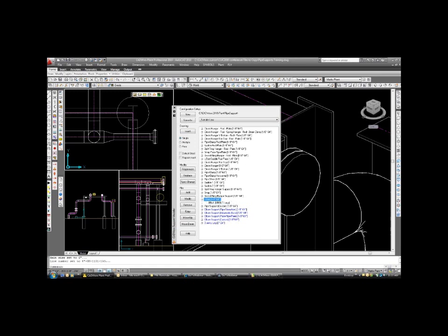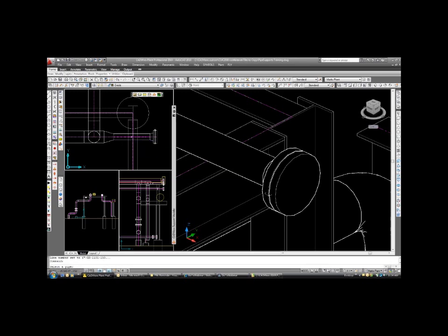Now let me explain one thing. These data files can be in different assemblies. If I go up here and show you the clevis rod hanger at the very top, you see there are a series of 3 support data files that come in, and that completes a complete assembly of that rod plate hanger. Right now, we will just use a single U-bolt, single support assembly data file, and we'll use a single insert and just say insert.